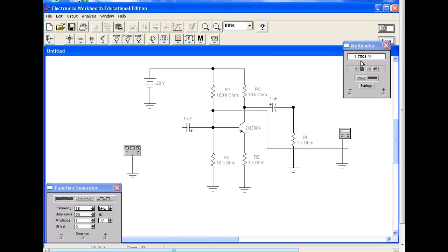So 1.5, 1.75, that's pretty good. And we calculated what? 1.8. Okay. Now this guy, we should expect it to drop around 0.7 of a volt. If I can disconnect, it's probably easier to disconnect it over here. Or at least I thought it would be. There we go. And then measure right here. Measures about 1.1 volt, 1.08 volt.